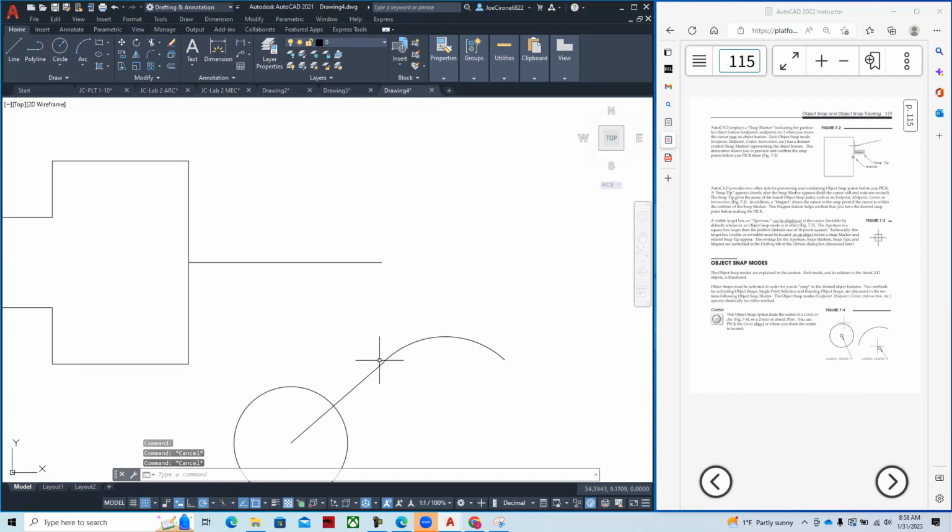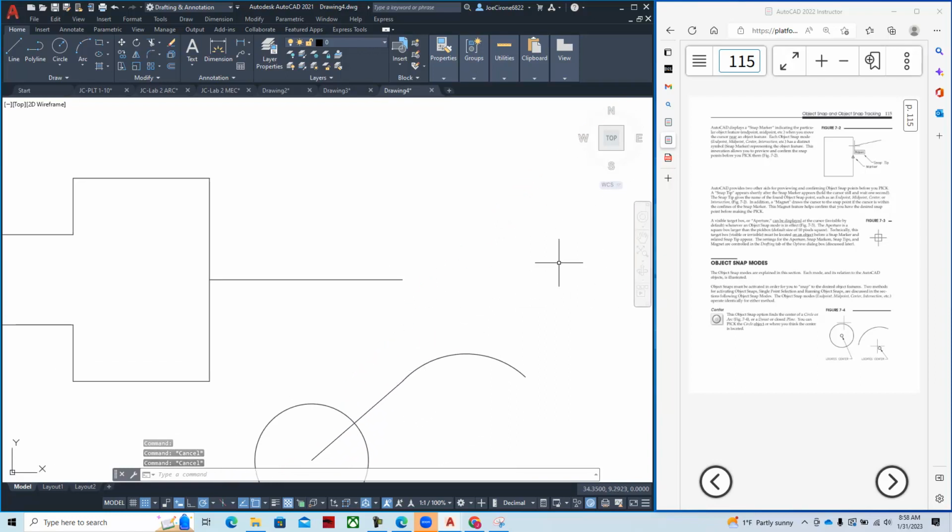And that's the thing. If we're working with CAD, what they want you to look at is the accuracy. And so if I don't have any snap and grid and I just draw a line, it's going to be that distance, 6.2155, which is very accurate. But if I just want a 6-inch line, then I'm better off to either go with line and polar, track that out, type 6, enter, and now it's exactly 6 inches to 4 decimal places.